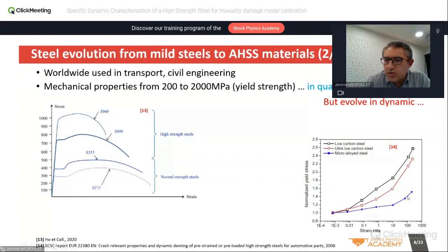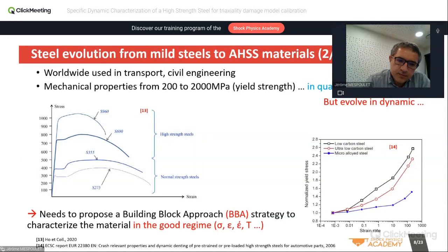So it shows that depending on the strain rate and the conditions where the steel will be employed, sometimes it can be more effective from an economic point of view to select a steel that is a little less effective in quasi-static, but has more capability to respond in dynamics. That's why dynamics is very important if you consider, in our case, some defense applications.